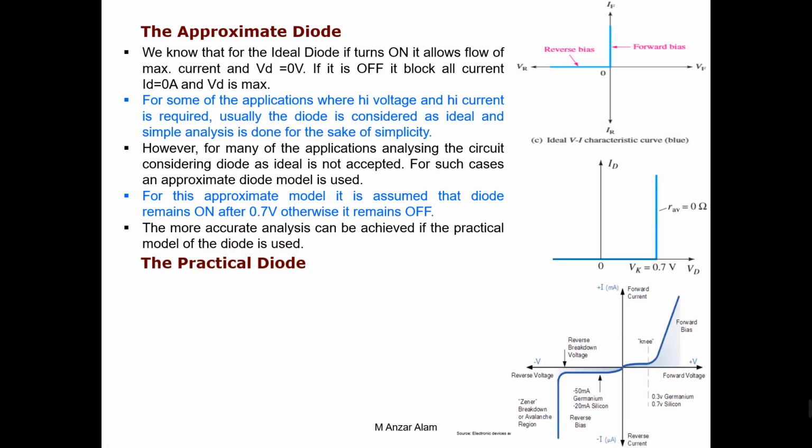Okay, so this is the real diode or the practical diode. It has different regions. It means the forward region, the knee, the voltage from 0 to knee, and knee to forward region, and then we have the reverse region, and we have avalanche breakdown. It looks like this is quite different from this one and this one. Yes, it should be, because this is a real diode. This has no assumption. This has no exemption. This has no voltage, and the current is considered negligible here.